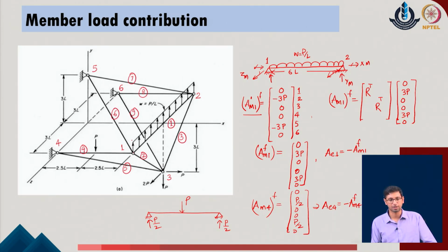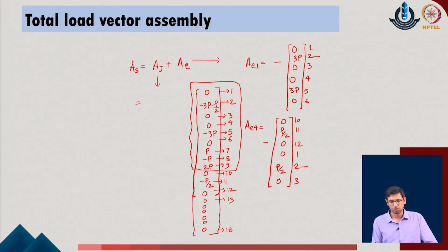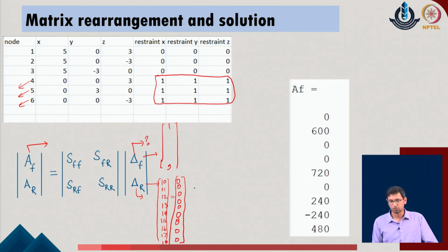When they come out with the reactions, they will be downward in the given problem. So, accordingly these member forces will actually be coming out to be positive. You can see that the load direction is upward, which means that the reactions will be downward in the system, which are negative, and that is where the member forces will come out to be positive. Okay, fine. So with this idea, we can get the individual values of these forces.